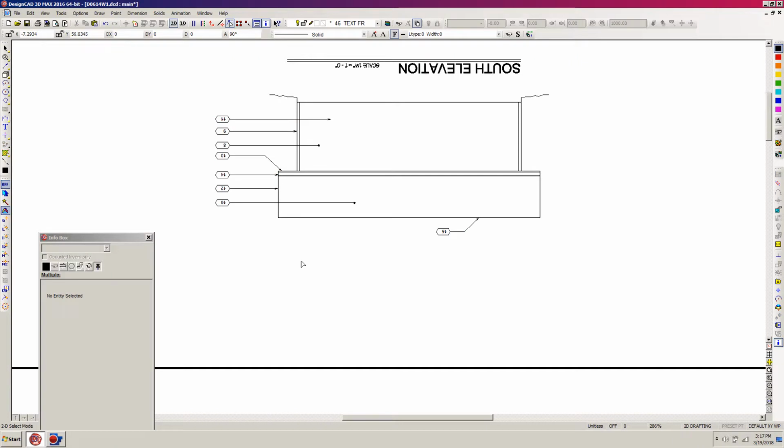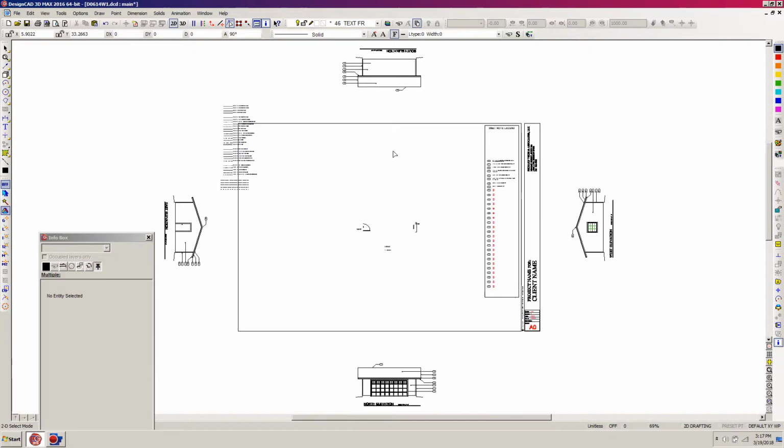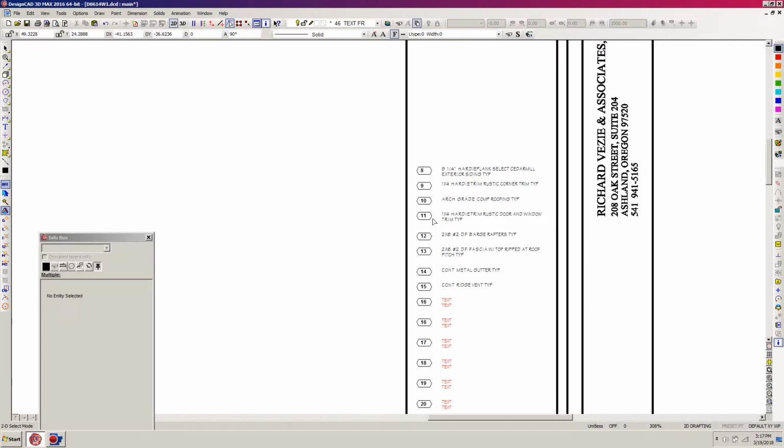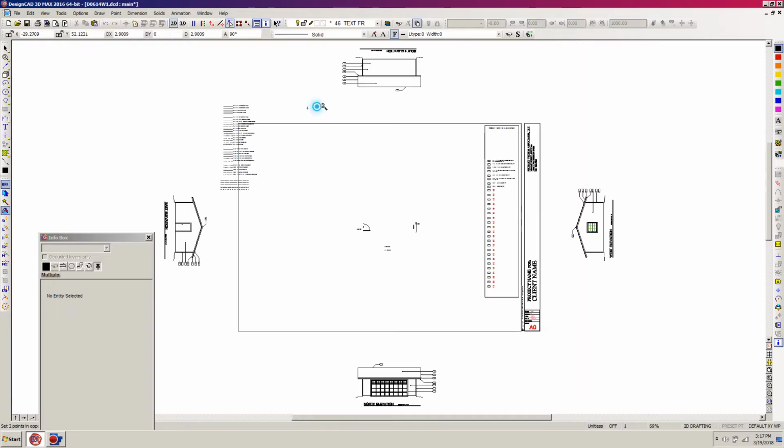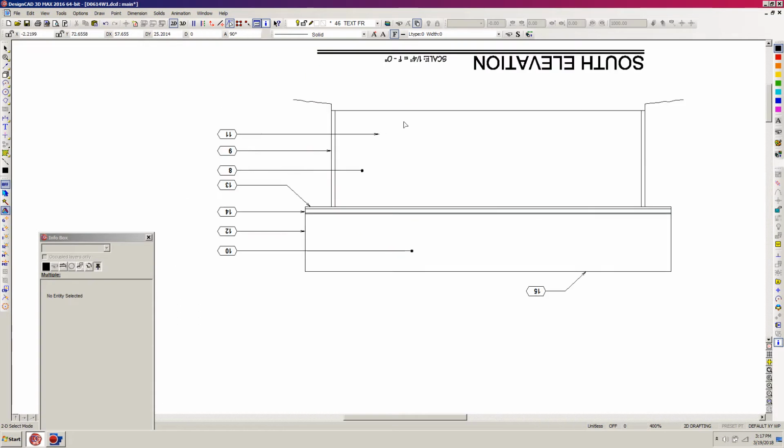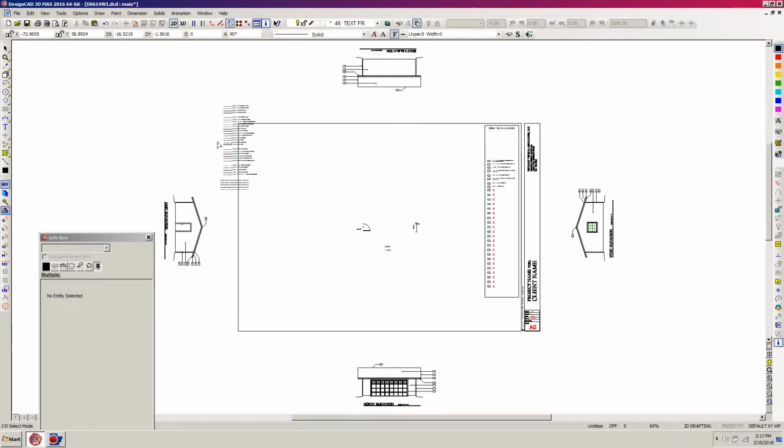And now one of the things that's going to be kind of clear here is there are no windows or doors on the rear elevation. So Control W, zoom up to see which number is the window and door trim, and it is sheet note 11. So Control W, hit Z for zoom, zoom up on this rear one, and just eliminate sheet note 11. Select it and hit delete. Okay, Control W. Now those are all in layer 50. They're in their proper layer.